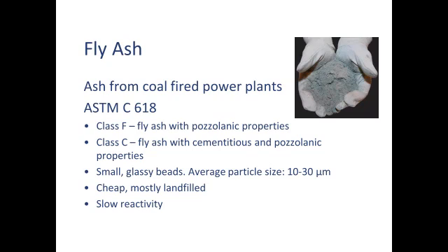So instead of, let's hypothetically say, I want to make a 4,000 psi mix or 4,500 psi mix, which would be 30 MPa in round numbers, and that's all I need. Okay, so that might be a driveway, that might be a house foundation or something like that. You can order concrete made with 100% Portland cement that does that, and it's going to cost a certain amount. But if you ordered it with fly ash as a substitute for some of your Portland cement, the per volume cost of that concrete is going to be lower. Now the end result, the 28-day strength of that concrete might be the same, but the early strength is going to suffer. Fly ash has a slow reactivity, so you're going to lose early strength. It tends to be used in high substitutions.